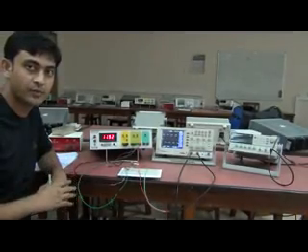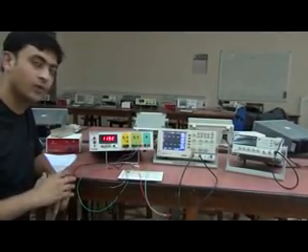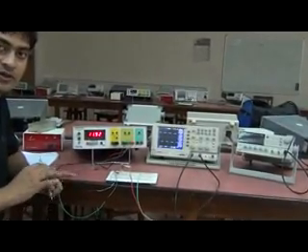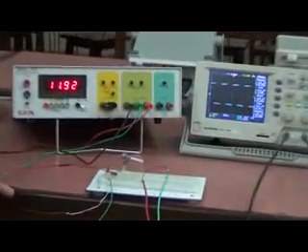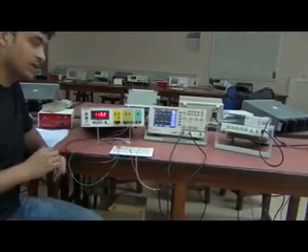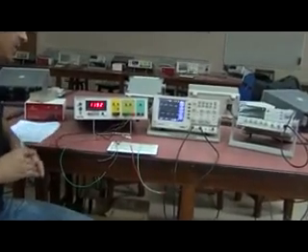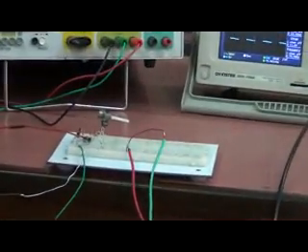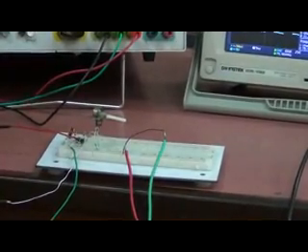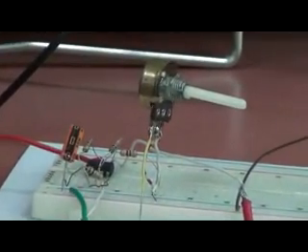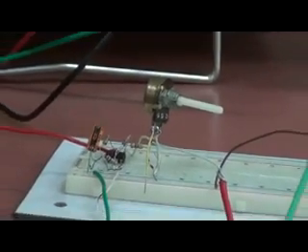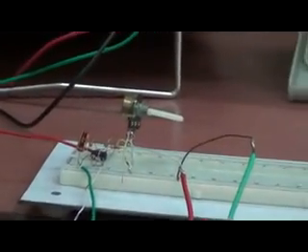The next part for this experiment is observing the astable multivibrator circuit output. Since the Astable multivibrator circuit doesn't have an input, it generates an output. The specification for the resistor and capacitors are mentioned in the handout. We are using a 10 kilo ohm potentiometer so as to vary the frequency for the output. Again, we are generating it using the op-amp. We can observe the output of this Astable circuit on the DSO.